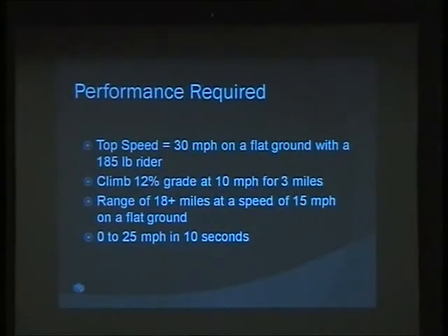What is the depth of discharge of the battery? At the end of 15 kilometers or 18 miles of range, how much would it have discharged? If your depth of discharge is more than 35%, the life will come down.